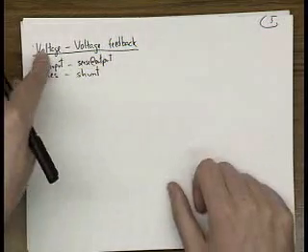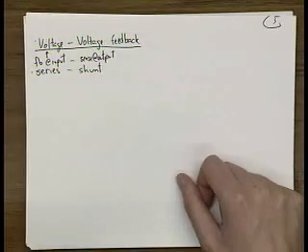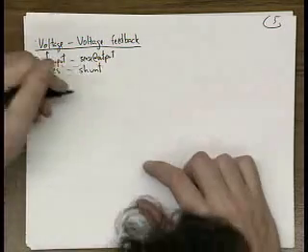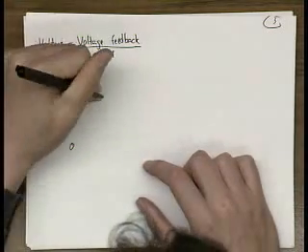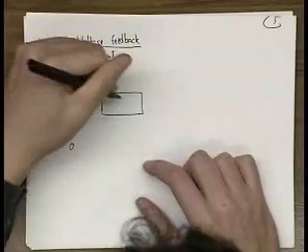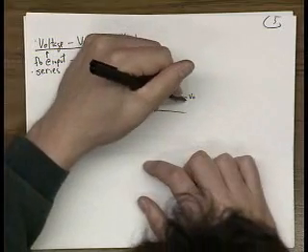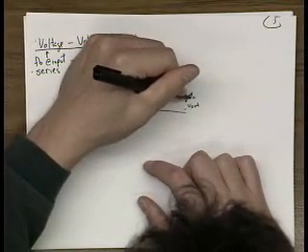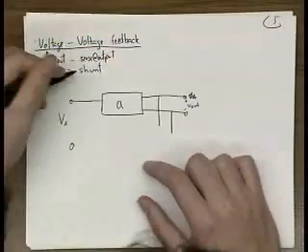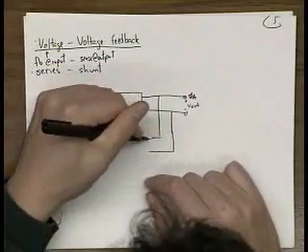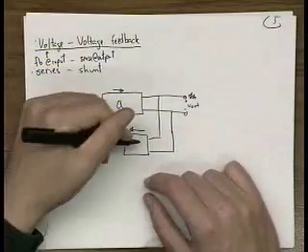And always the first term refers to what's fed back at the input, the second term refers to what's sensed at the output. So what will this look like in terms of general blocks? So we'll have some V input here. There will be some active circuit that creates a V output. Okay. We shunt off this output because it's shunt. Feed that into a feedback network. I'm drawing arrows to indicate the direction of the action.